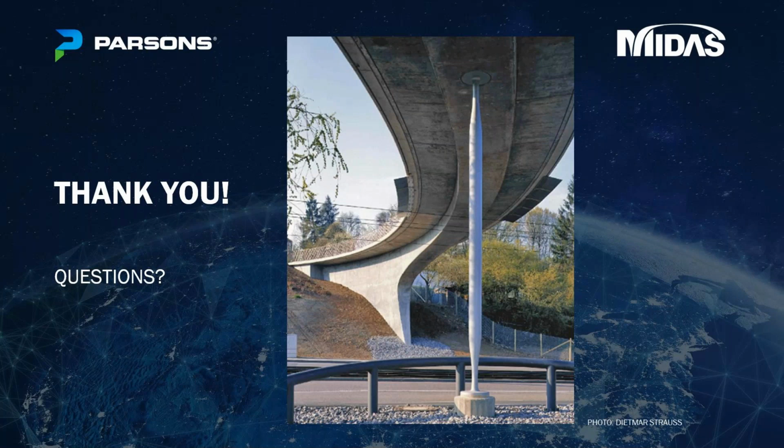So that bridge that I showed in Winnenden, where we needed the tendons in order to counterbalance these self-anchored forces, they make the bridge very stiff. So you have to cope now with all the deformations at the abutments, and that's why we have these approach slabs there. So you need to be aware that when you have a post-tension or a pre-stressed system, the bridge is stiffer and cannot accommodate some of the temperature movements with cracking. And as I said, stiffness is something that can hurt you in an integral bridge. Yes.